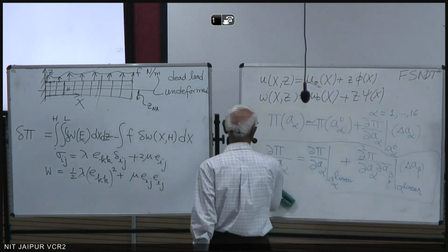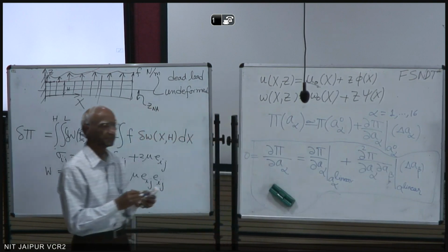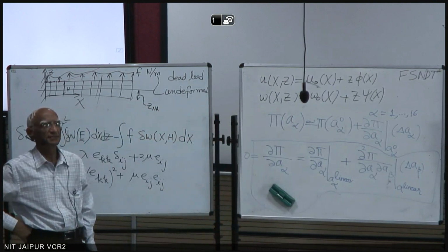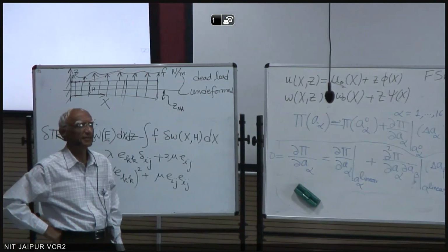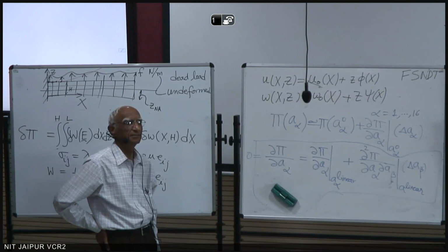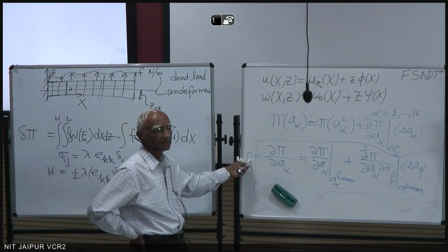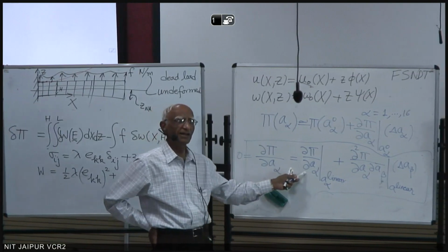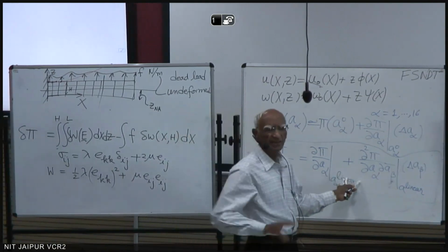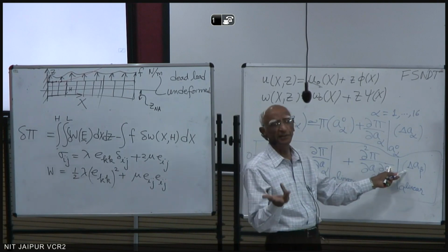So we have to solve these equations. This should be 0. This becomes the force vector. This becomes the so-called stiffness matrix. And this is the increment.